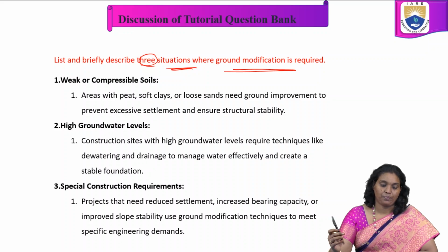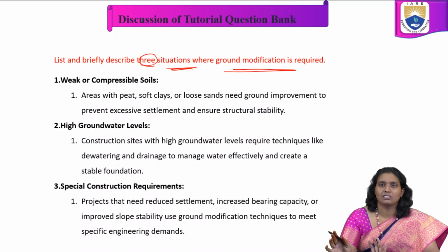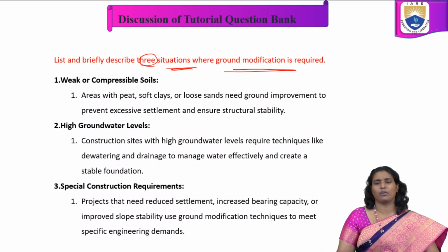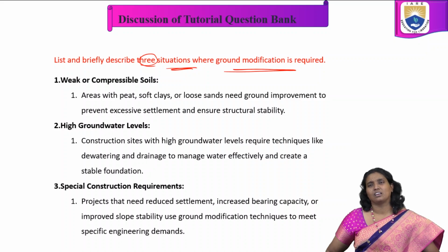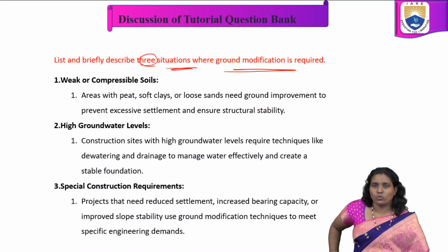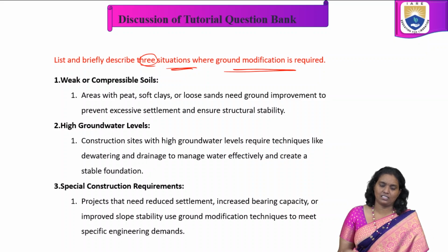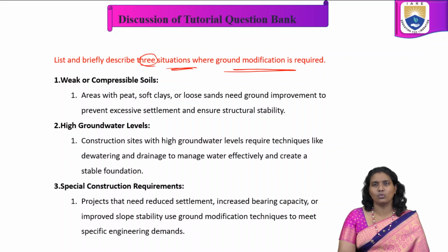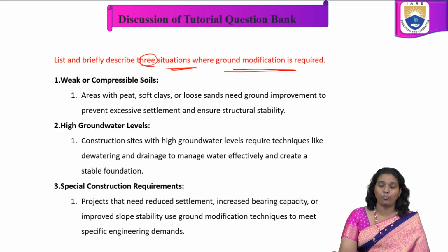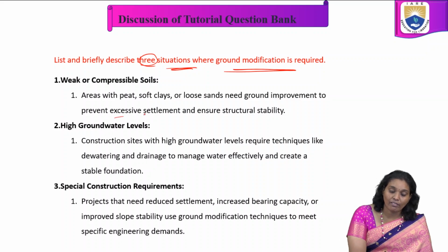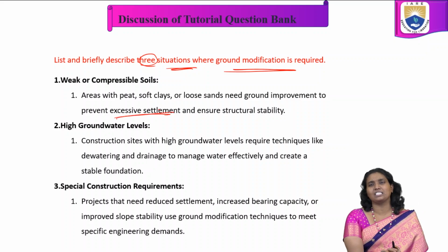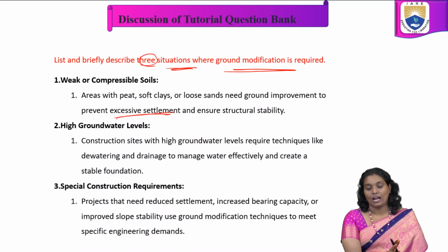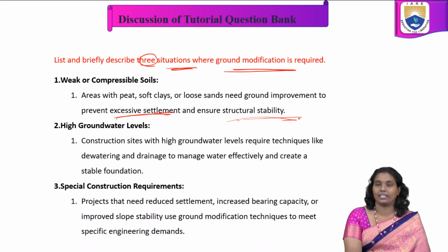So in weak soils, it is a very, very important thing. In these weak soils, mostly soft soils and loose soils are there, loose sands. In such areas, soft clays or loose sands need ground improvement to prevent, in most of the cases, excessive settlement and also to ensure structural stability.